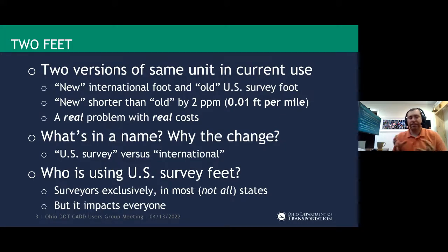Like the name says, U.S. survey versus international feet, that change really stems from the National Spatial Reference Frame and its transition towards the international foot, making everything a little bit more uniform throughout the world, instead of having this singular definition for geodetic type surveying purposes.